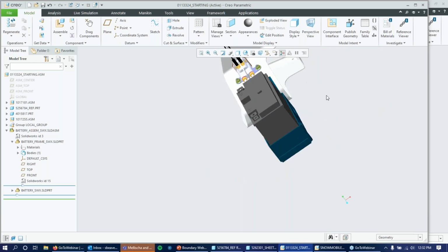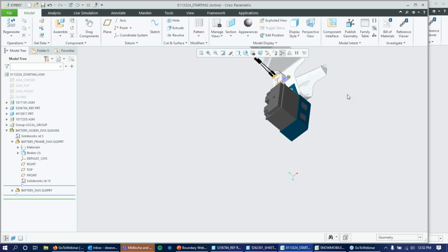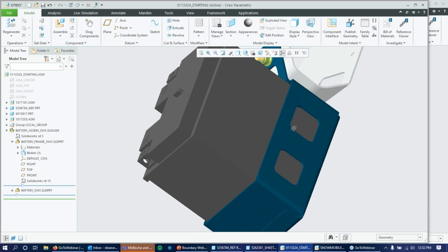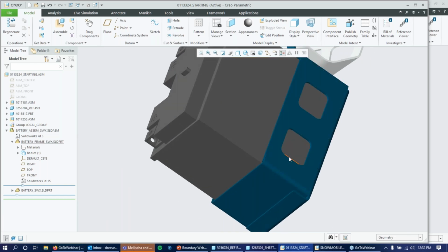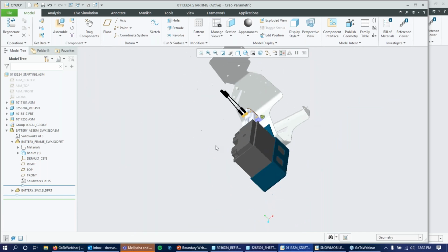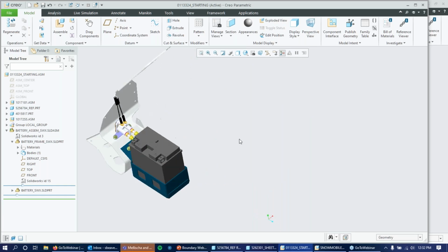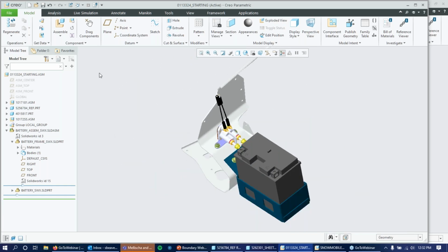The sheet metal parts are usually, as I said, very compatible with flexible modeling. For example, if I was to edit this hole, I could extend it to the end of this hole to create one large cavity and make rather large edits without actually having any of those features in the model tree. So I hope that answered your question, but yes, it's definitely flexible modeling.